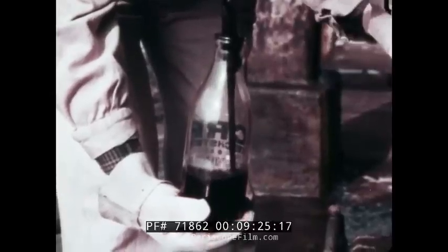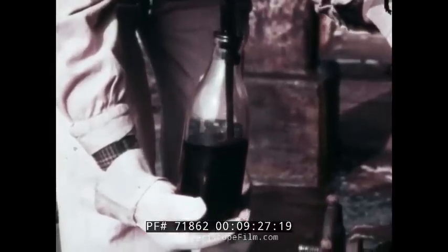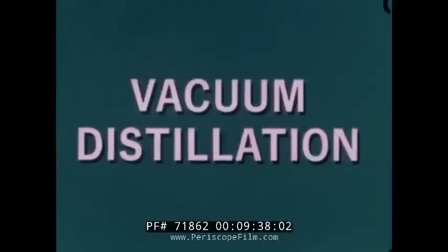The fractions in the residue boil at very high temperatures, some more than 1,000 degrees. At these temperatures, the molecules will crack apart before the fractions boil. To prevent this, they must be made to boil at lower temperatures by vacuum distillation.